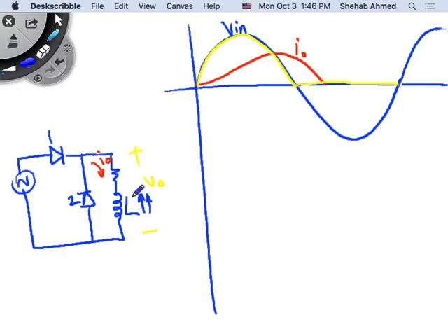No. If I increase inductor, what is this going to do? If I increase inductance slightly, what will change in the waveforms? Which waveform will change? The red, yellow, or blue? The current will change. Only the red waveform. What will it do? It will move to the right. Keep moving to the right. Okay. At some point, what happens here?